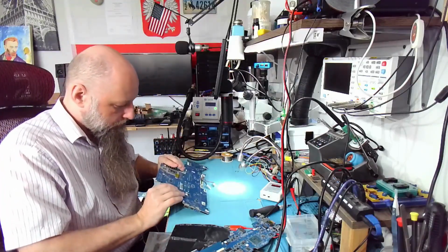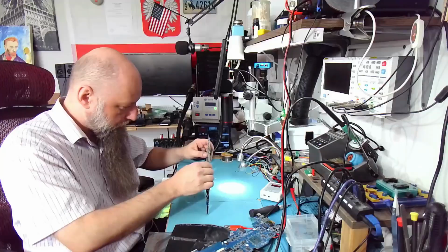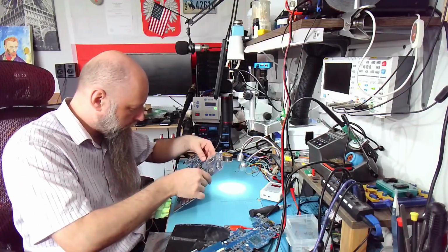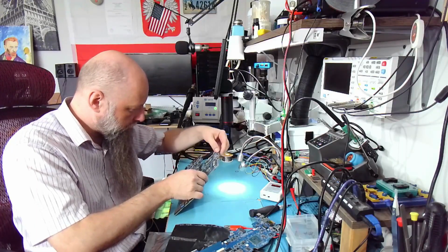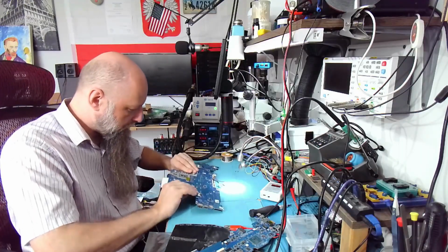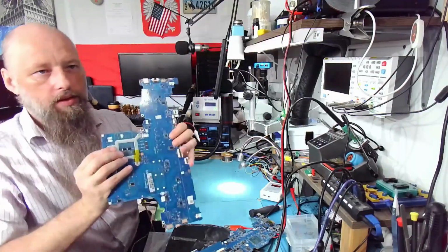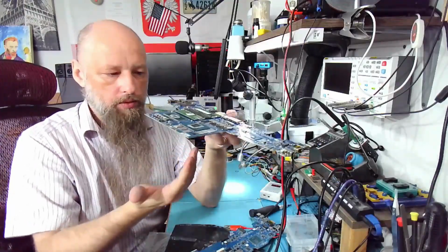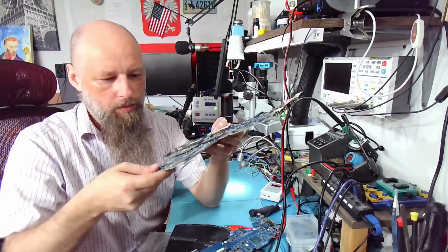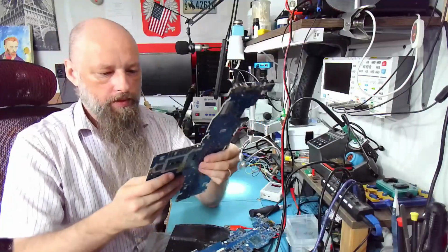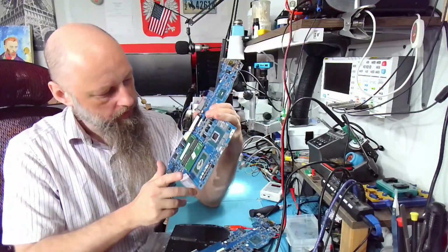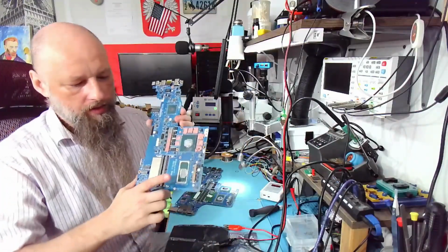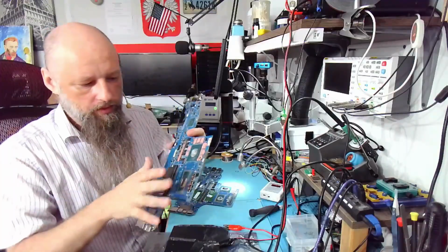Now this, well, there's no supports on the CPU, which is good. That backplate behind the GPU could fall during the procedure. Most likely it will. We probably need to remove it beforehand because these are typically glued on, and as soon as I put it on the preheater and preheat it to 210 at the bottom, it will just drop. So that needs to be removed. Then we need to remove this CPU, re-ball it. Then we need to remove the old CPU, clean the board, put the new CPU on.